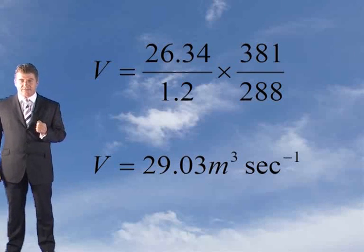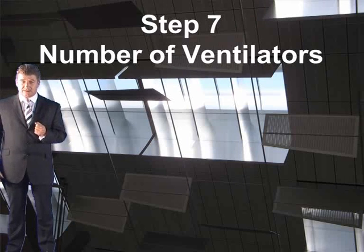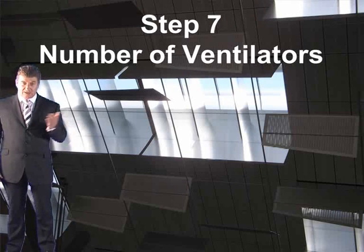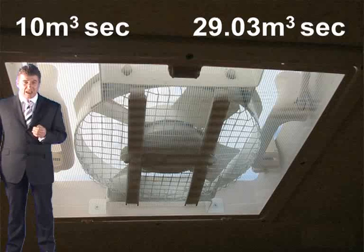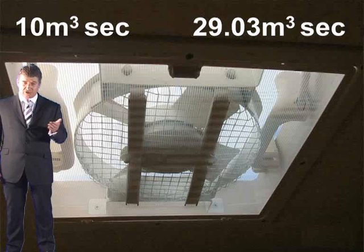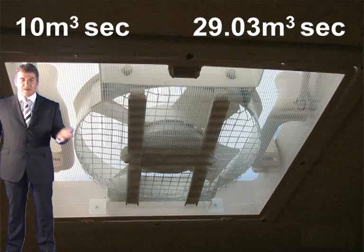We've worked out the volumetric flow rate. Now we're going to look at step 7, determining the number of ventilators. Now it's proposed, as we said in the question, that fans with a capacity of 10 metres cubed per second are going to be used. Because the automatic fans will be located in an atrium which will have no fire loading, it can be assumed that no fans will be lost in a fire. We also know the volumetric flow rate is 29.03 metres cubed a second. With fans having an output of 10 metres cubed a second, we need 3 fans.